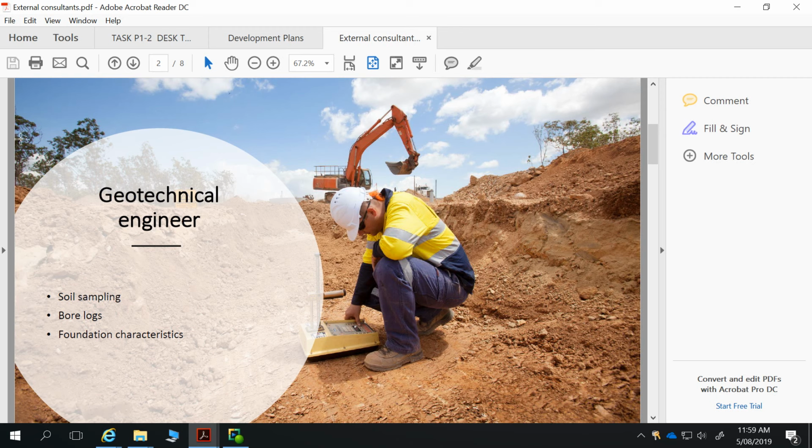Whenever we're doing a development, if we don't have any soil samples for the site, we have to take a minimum of 3 core samples. I think the depth is base minimum 3 meters, but the company I used to work for would specify going down to 4 meters. That was in excess of the base requirements, but in South Australia we have reactive soils that go down quite a long way. We've got clays which take in moisture and swell up, and some of that swelling can happen down as deep as 4 meters.